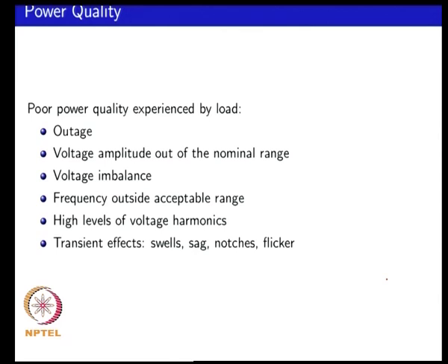If you are having electric supply, you expect your line to neutral voltage to be 230 volts, some nominal voltage. Typically a band around the nominal might be acceptable. You might have, say, a plus 10 minus 20% band around nominal considered acceptable power quality. If you go beyond that, you may want to disconnect rapidly.